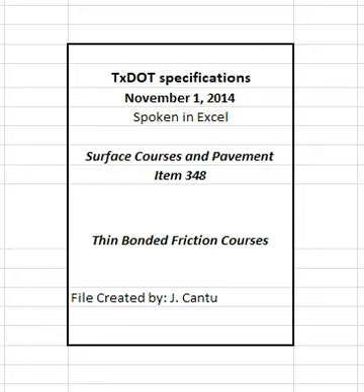Furnish a volume truck calibration and strap stick for the tank in accordance with Tex-922-K, Part I, unless otherwise directed. Calibrate the tank within the previous 5 years of the date first used on the project. The engineer may verify calibration accuracy in accordance with Tex-922-K, Part 2. 3.1.1.3 Screed. Provide a variable width vibratory screed that meets Item 320, Equipment for Asphalt Concrete Pavement.